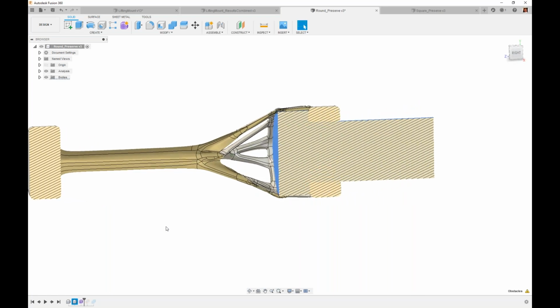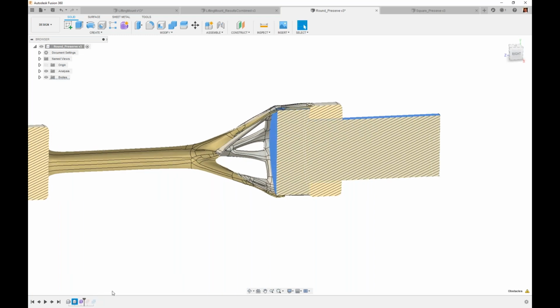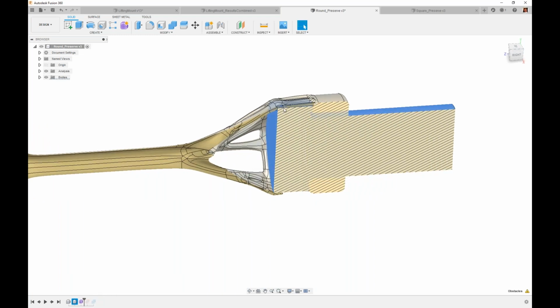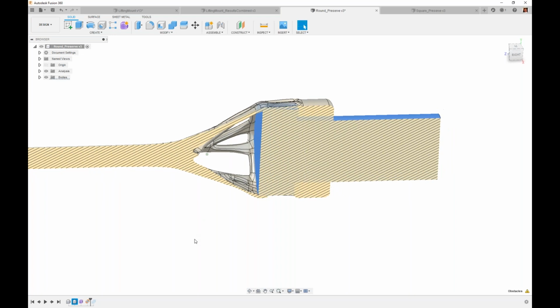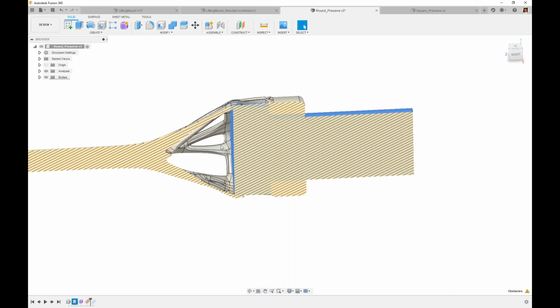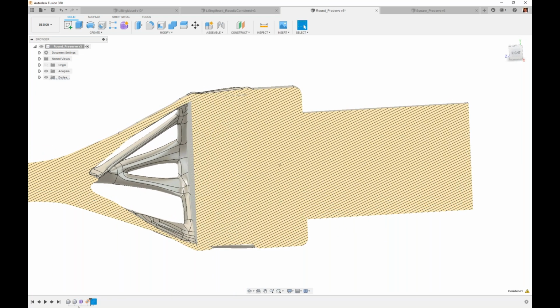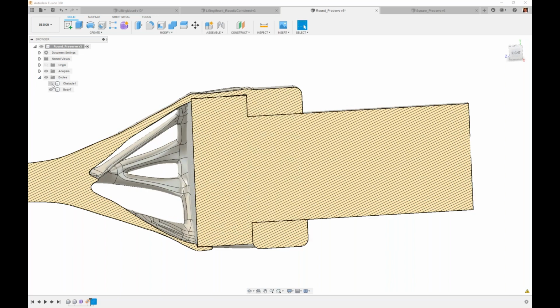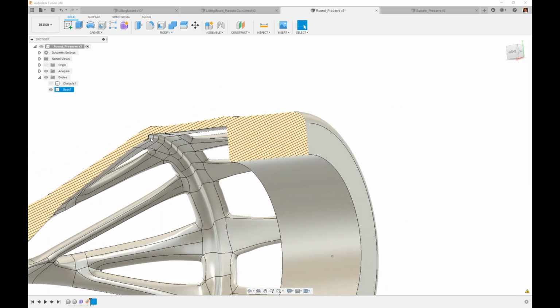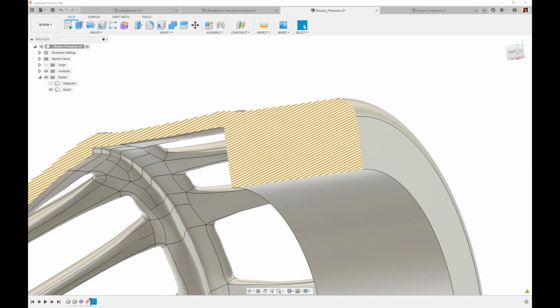The next step is actually to do a boundary fill and then Boolean out or combine to cut out this obstacle region. If technically my obstacle regions are slightly oversized, then this boundary fill is a little less required. At that point, I can have a cleaner shape by skipping and even suppressing this combine feature.